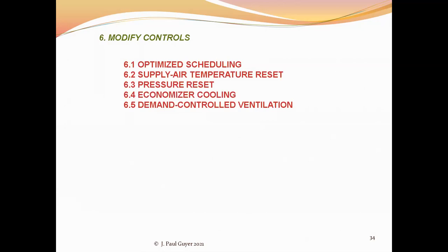And so you get free cooling as long as the temperature outside is right. And in this day and age, almost all systems include an economizer function, and this is a ductwork and controls function.